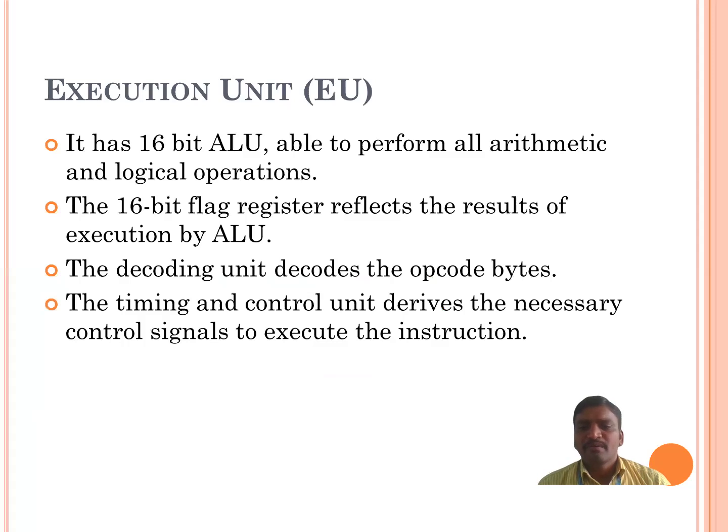After performing ALU operations or any operations, the processor cannot identify the result by itself. So it takes help from the flag register. According to the flag register, it can identify the result. That is the purpose for which we are using the flag register.